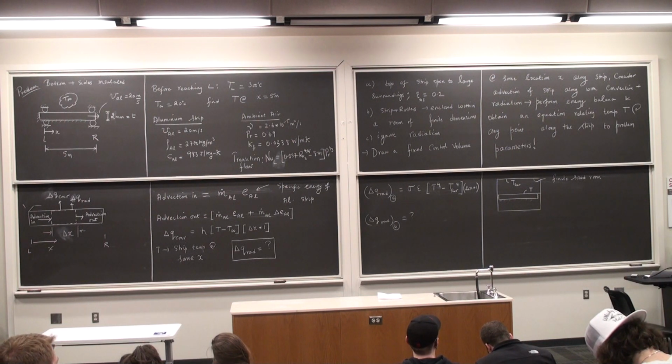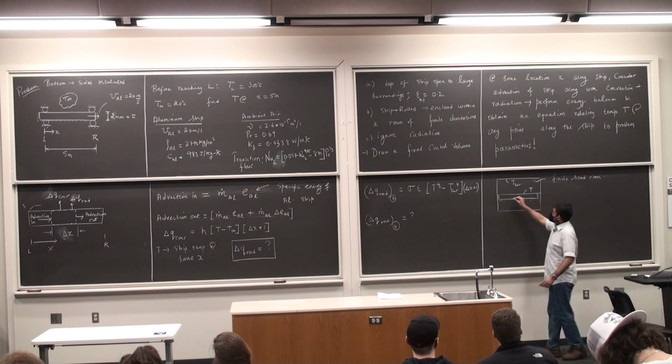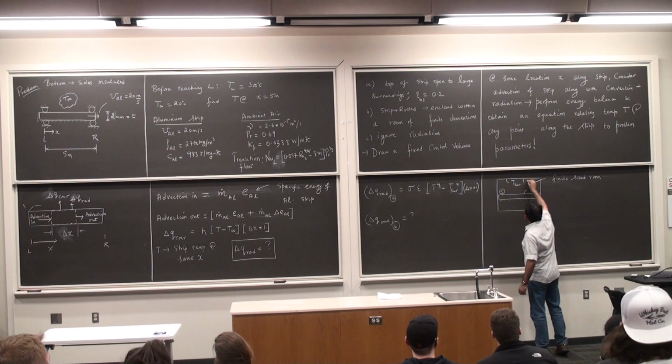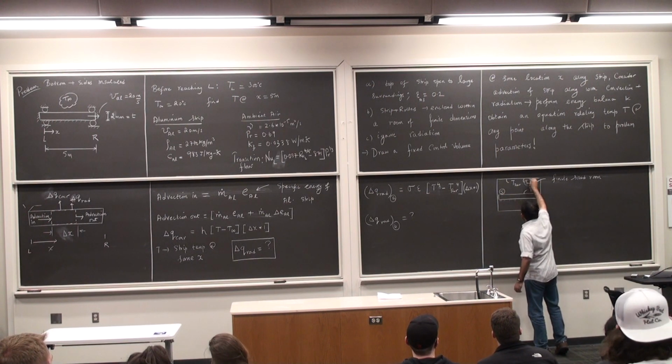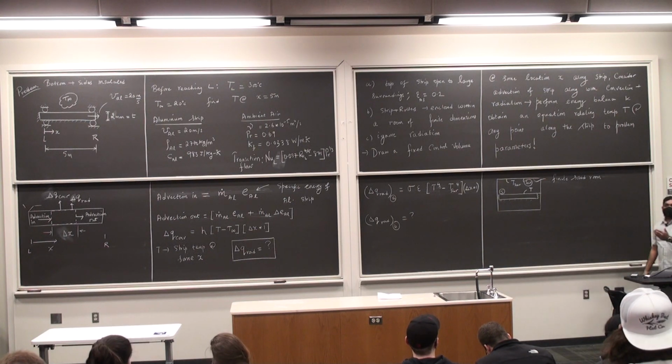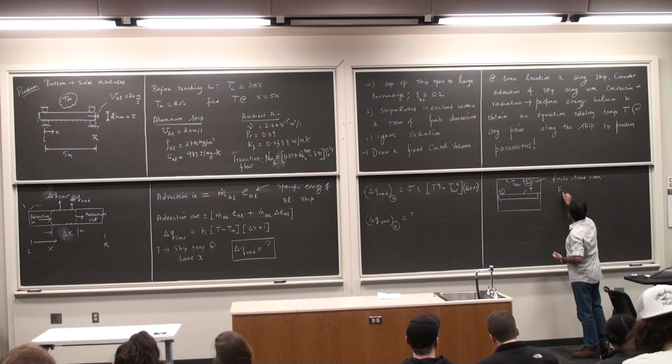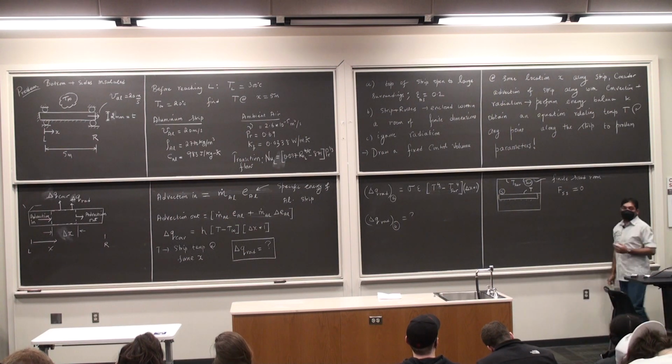Because it is finite, I have to consider the idea of view factors. So in this case, if I call this as the strip S, and this is the surrounding, it is quite obvious to notice that the view factor for the strip looking at itself is 0. So F S S is 0.